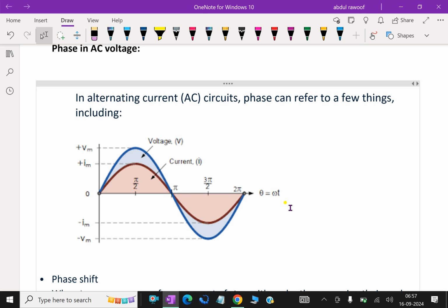When an AC voltage is applied to a pure capacitor, the voltage across it lags 90 degrees behind the current flowing through it. Current must flow before the voltage across and charge on the capacitor can build up. In more complicated situations involving combinations of R and C, the voltage and current are usually but not always out of phase. The angle by which the voltage lags or leads the current is called the phase angle.